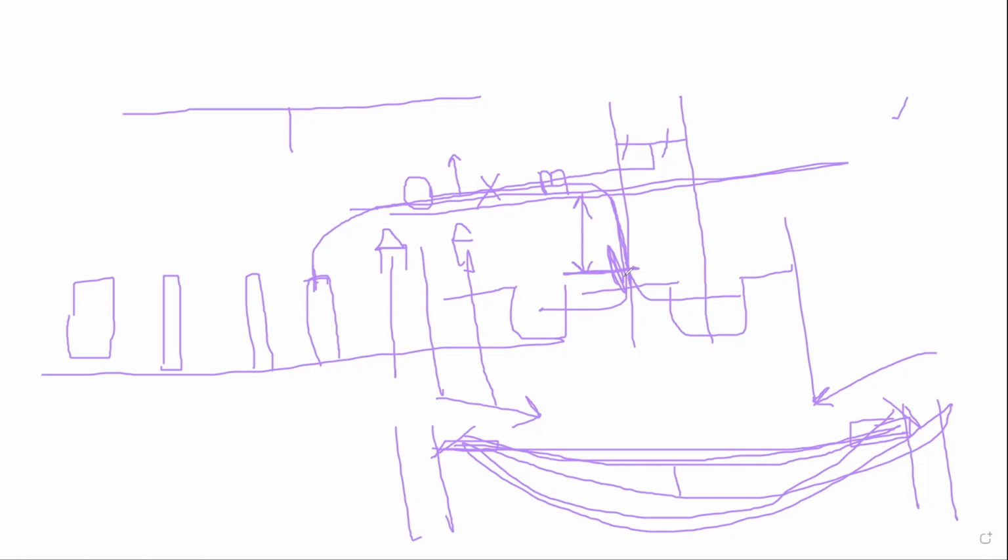Now, the sag calculation. Generally, as we discussed in the steps before, everything for the rigid bus will be applied here, except the last item, the couplers, because this is not a rigid construction. Instead of the couplers, here we have the sag. In the rigid bus, it's an aluminum pipe, so there won't be a sag. But here there would be a sag, because I am stringing the conductor between two support ends. So this conductor is free in the middle; it does not have any support.